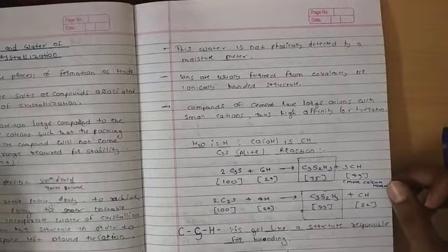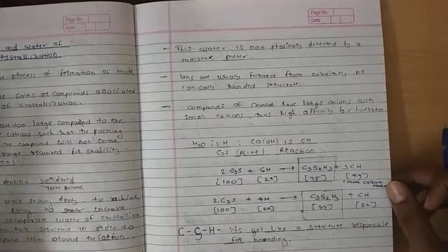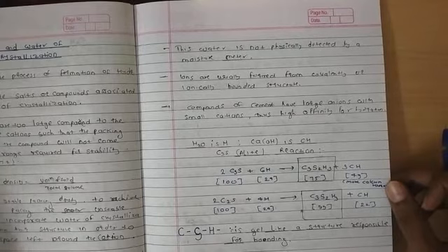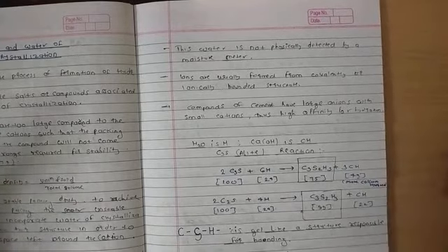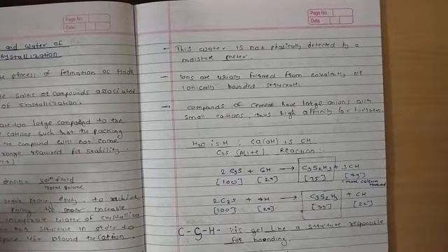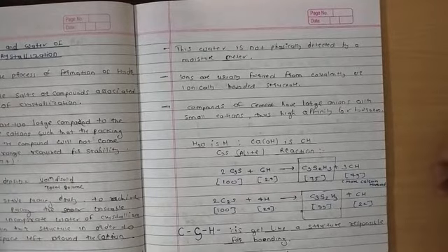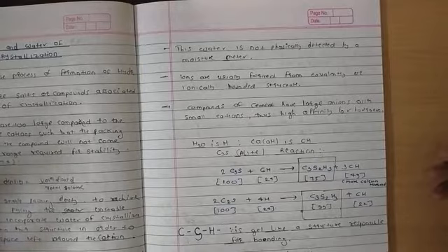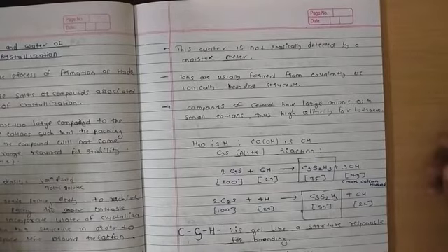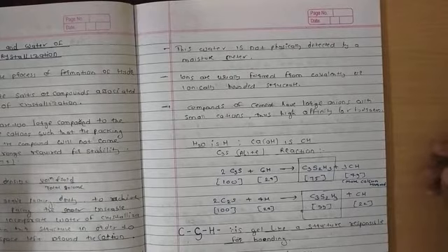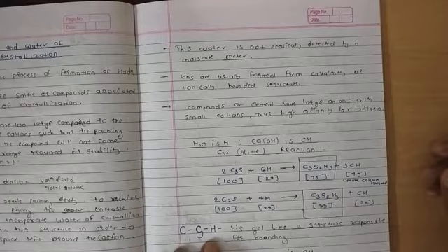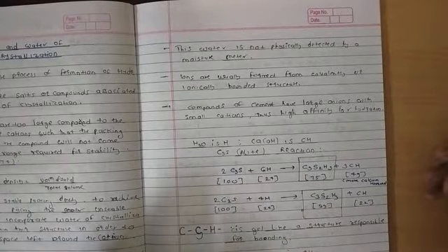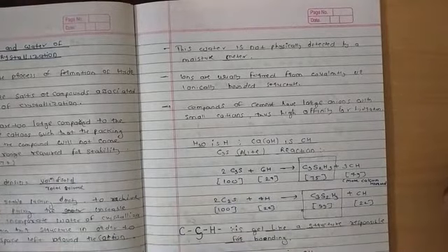Basically, in hydration, there are several compounds: C3S, C2S, Al2O3, Fe2O3. These compounds react together in several ways over time at the appropriate temperature, and they form the gel-like structure which is known as CSH gel. It is not the exact chemical formula for the compound. It is just for the sake of ease that we write it as CSH.